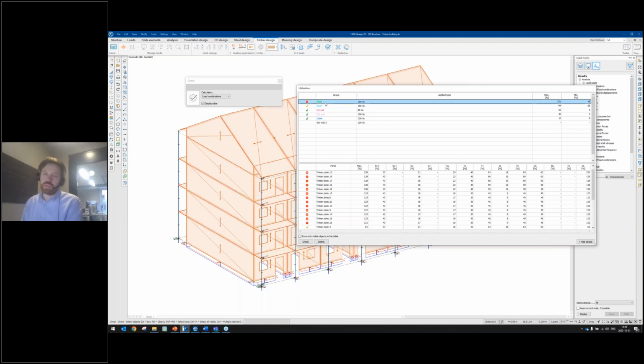When you're doing an auto design, each member in each group will have the same section. So it will take the worst case for that group and design. However, the design won't take into consideration the deflection. So the deflection needs to be handled manually somehow. It will only take into consideration the other checks for the ULS.